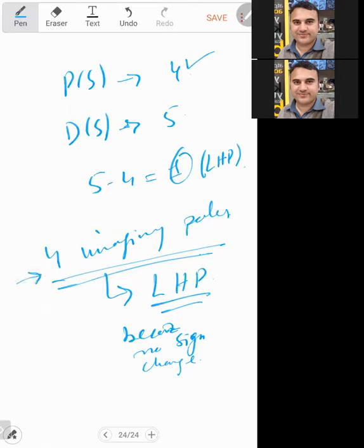If we have the imaginary pole 1, it has a symmetrical partner over here, at the same location but on the negative imaginary axis. So this means that we have 4 poles on the imaginary axis, and 1 pole along the left half plane. The location is not known, but since it is 1 pole, it has no symmetrical partner. If it has no symmetrical term, this means that it is along the real axis. So we should know about that one also.